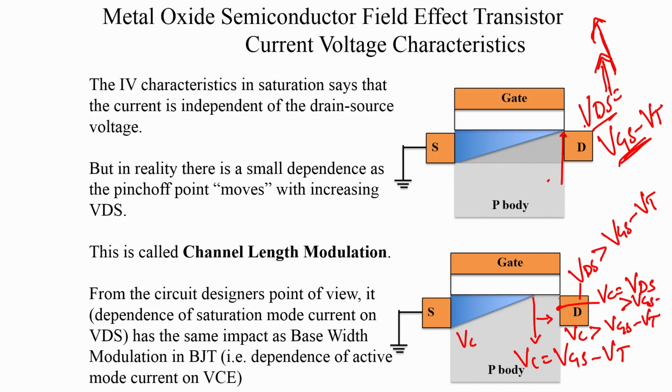So, the pinch off point now relocates to a different region, and as I keep increasing VDS, the pinch off point will start drifting towards the source side, right.